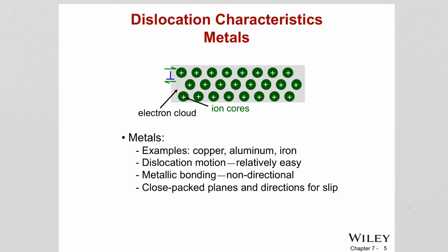So where do these dislocations come from? They can be introduced during the processing of the material. For example, we do casting for metals. There is the molten metal, and then it solidifies. So during solidification, these defects can form. During plastic deformation, the number of these defects increases. In fact, when we do deformation, we are increasing the number of dislocations.